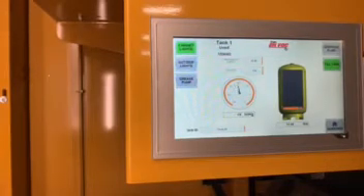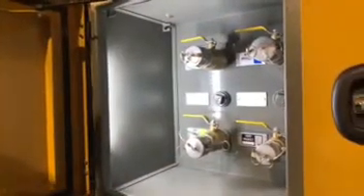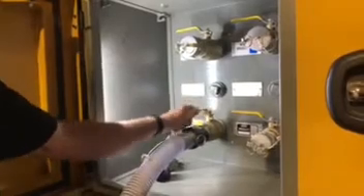Once we hit 20 inches of vacuum, we'll go around to the other side and start loading oil on it. Once you have 20 inches of vacuum in your tank, you can start filling your truck with oil. You use the supplied barrel straw, connect it to whichever tank you want to be able to load the oil into, turn this ball valve, and you'll load the oil onto it. You'll repeat this process for each new fluid tank.